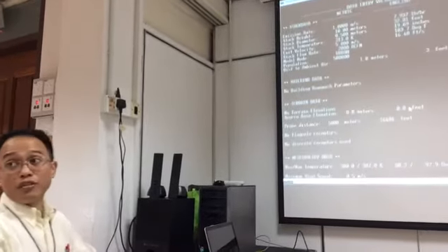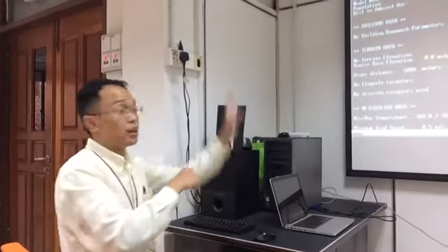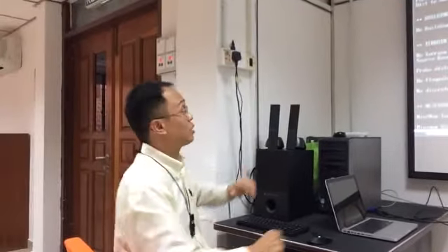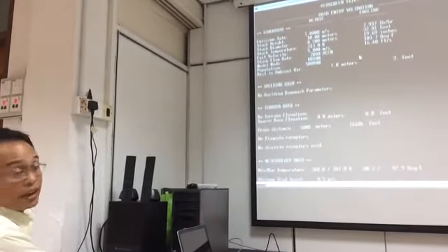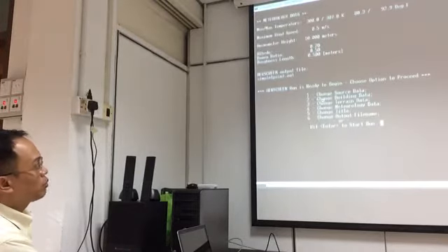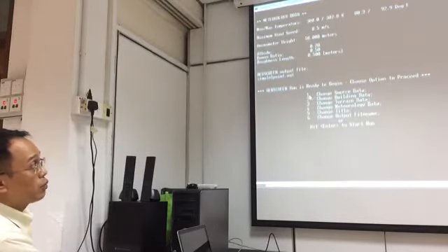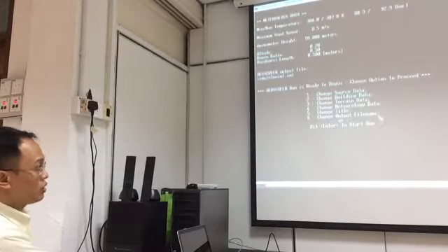So this is the summary of the data that you input into the software. It's not the run of the model yet. It's a summary, so you can double confirm the values that you put in. At the bottom here, you have a few options. It says AERSCREEN run is ready to begin. Choose option to proceed. Whether you want to change anything, maybe change the source data, building data, terrain data, no. If you don't want to change anything, after reviewing this, everything is correct, then you just press enter.